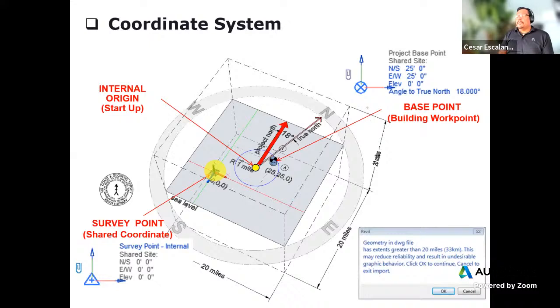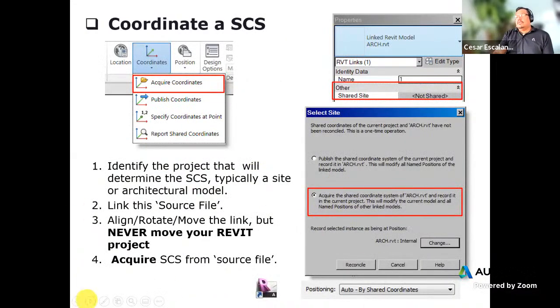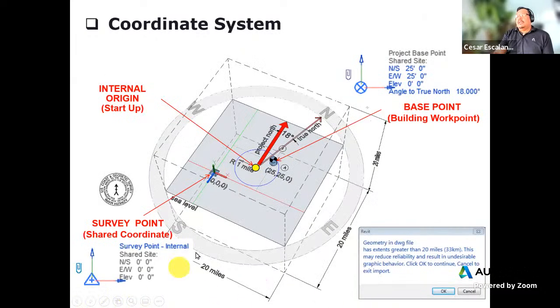And it's a little inconvenient to use that as a 0, 0 for a project. And so when you talk with your civil engineer, you agree on a point that is close to the project that you can use as an insertion point, and then the civil engineer agrees on re-exporting a version of the civil file suitable for Revit consumption.